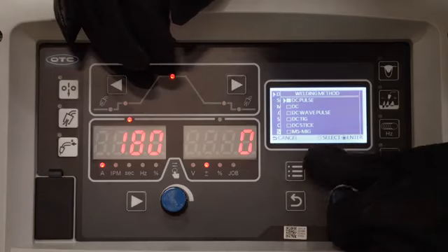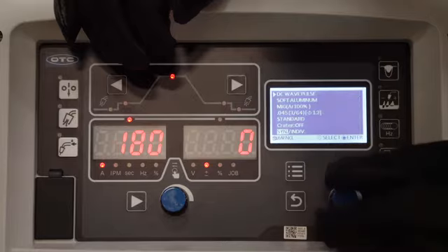This is a video focusing on aluminum wave pulse. So we have two different welds, one made with a frequency of 3 Hertz, one made with a frequency of 1.5 Hertz. Gives us the ability to tailor the finished weld to give us the appearance that we are looking for.